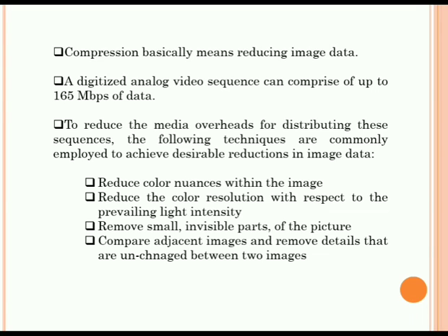To reduce the media overheads for distributing these sequences, the following techniques are commonly employed to achieve the desirable reduction in image data: reducing the color nuance within the image, reducing the color resolution with respect to the prevailing light intensity, removing small invisible parts of the picture, and comparing adjacent images and removing details that are unchanged between the two images.